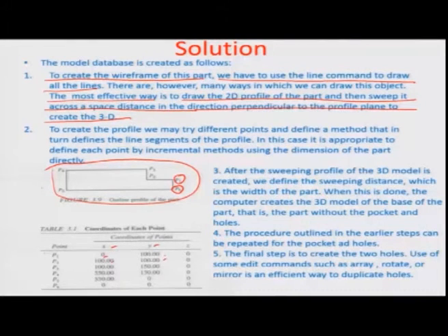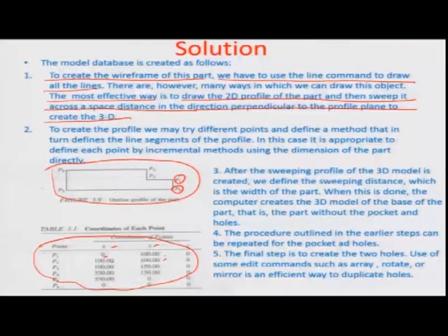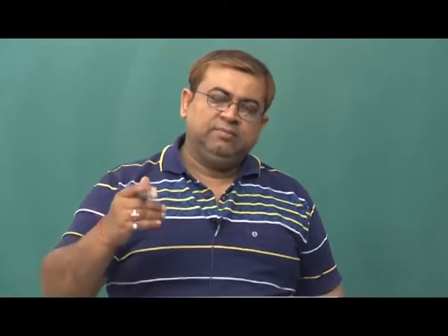So, with all the numeric data internally captured for these arrays of points P1 to P6, you could have the z data captured through incremental values of z from 0 to 300. Let us say it starts with z equal to 50. So, you have z 50, 100, 150, and all these different P1 to P6 planes, this geometry would repeat itself at 0, then at z equal to 50, then z equal to 100, and so on and so forth up to z equal to 300. So, you can have a series of these parallel planes P1 to P6, which would represent in turn the solid geometry.